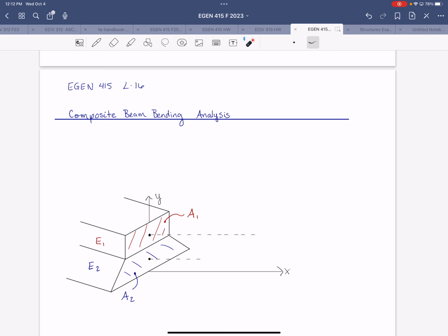Whereas in the approach in mechanics of materials, you probably transformed the geometric section according to a modular ratio based on Young's modulus. You can certainly apply that to more than 2 materials, but it can get a little bit cumbersome and complicated, and you have to calculate the moment of inertia multiple times. So this method is, I think, a lot cleaner and easier to apply.